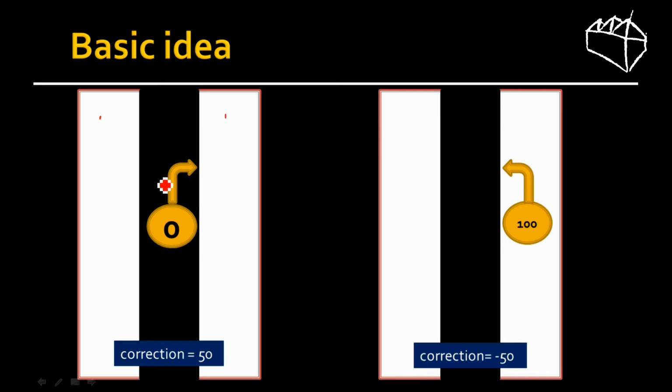So you have to follow the edge, because then you only have one black side, one white side and all values in between. How you do this is you have a switch in which you decide: if it's less than 50, then turn to the right, and if the value received is bigger than 50, so it's on the white side, then turn to the left.